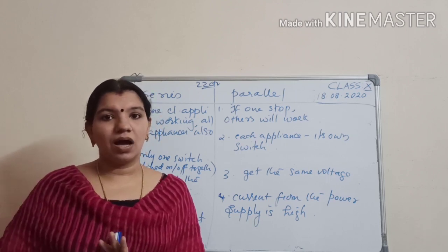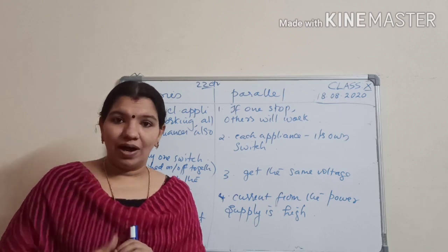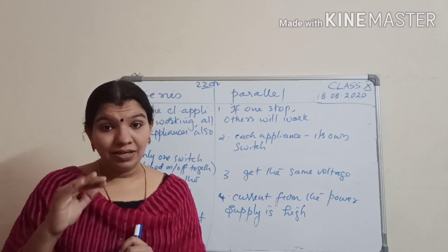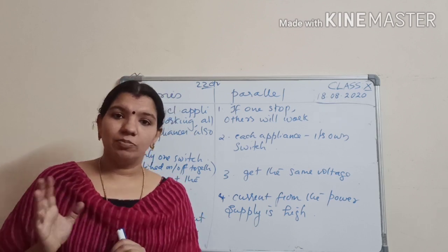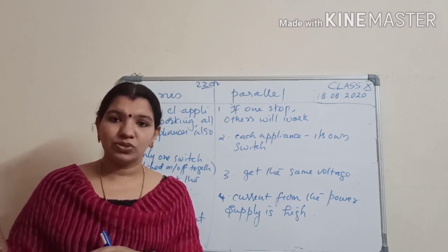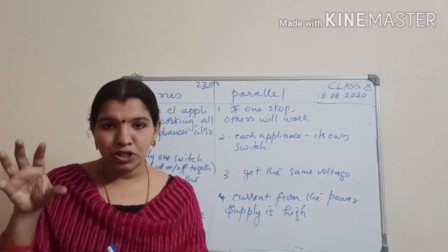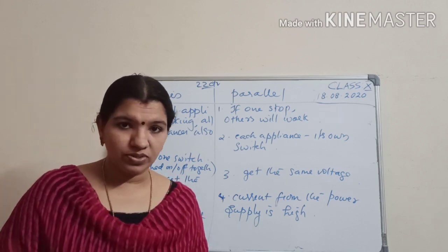Consider three resistances R1, R2 and R3 connected in series. Then V voltage is provided and I current is flowing. But in series combination, the voltage will get split and the current will be the same. Now to find the total voltage, I will take it like this, so and so. This type of derivation you have to write. It is very important and is asked for 5 mark questions also.